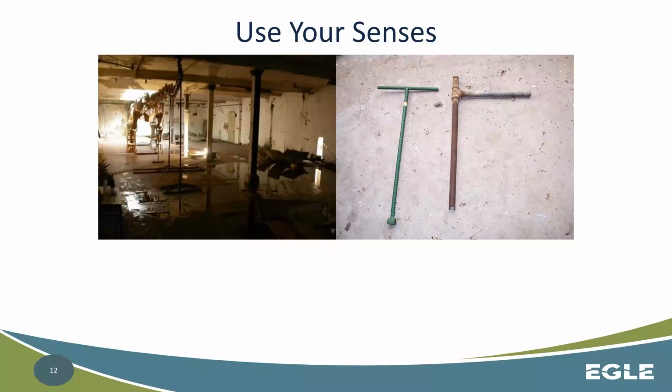You might end up finding out that the individual who lives in that property has put a blank in between your meters so that they can get free water, and then occasionally throws it back in to get a few readings so that it's not suspect. There's things that happen out there, or the contrary could be true. You could be noticing, this looks like a vacant house, doesn't look like anybody's here, but there's thousands of gallons of water being used every month. That could mean that there's a leak in that facility or there's something else going on. So it's good to be aware and present.